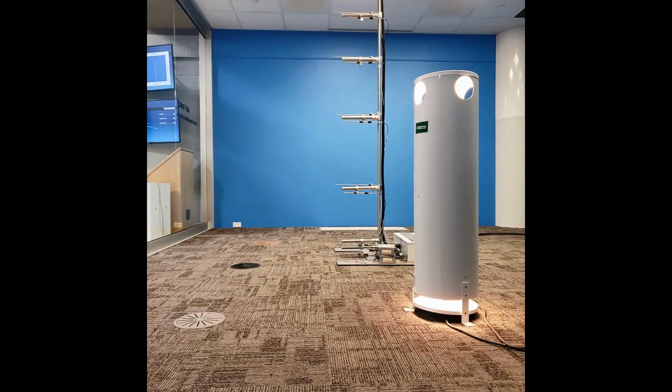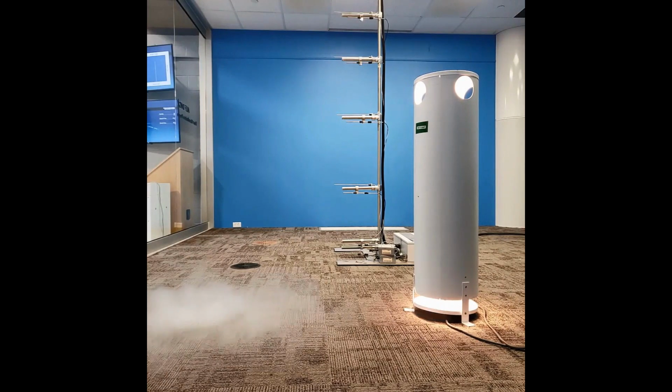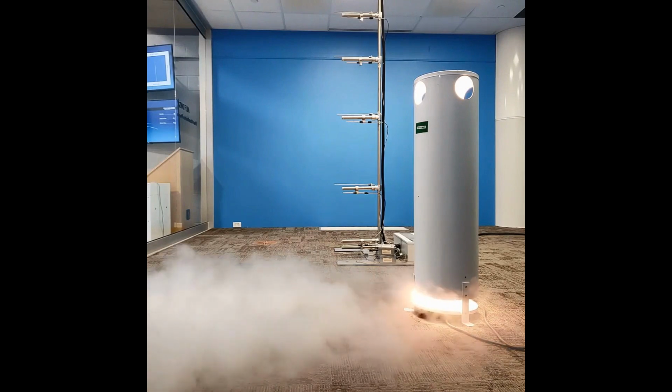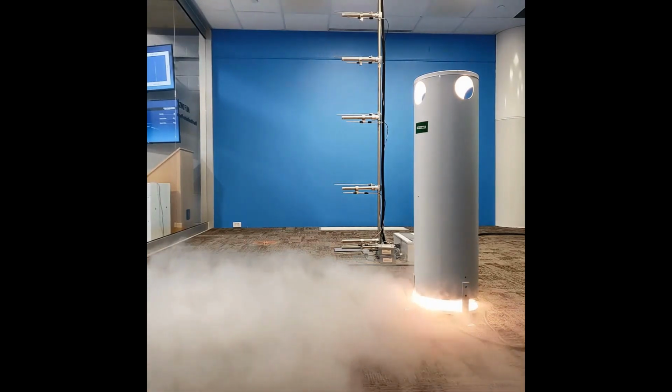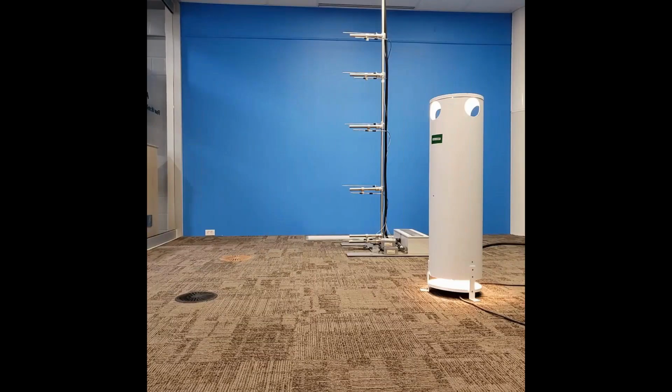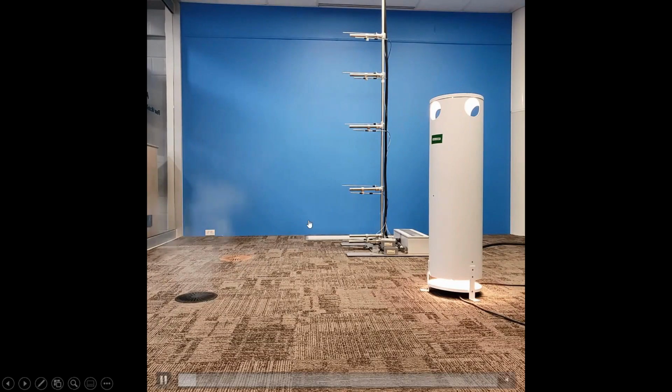Conference room, I say that because your furniture layout could be different day two. And so if a bunch of people run into a conference room and bring their chairs in and sit directly underneath a high throw diffuser, that's going to be pretty drafty. So this really is independent of the furniture layout, as compared to a higher throw diffuser.